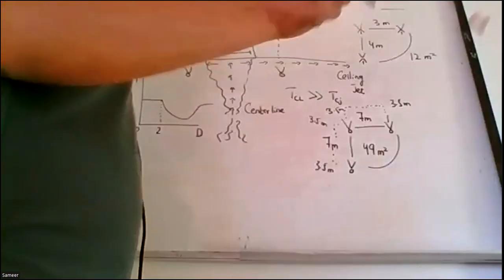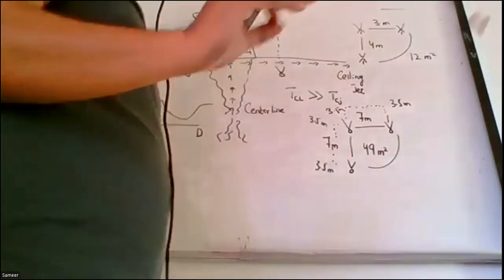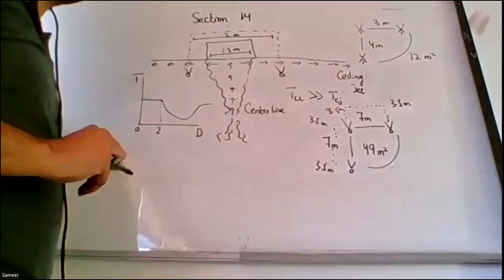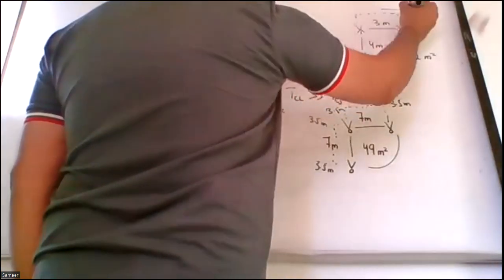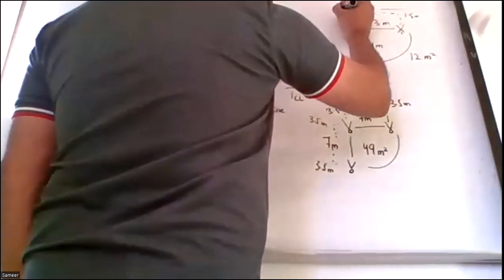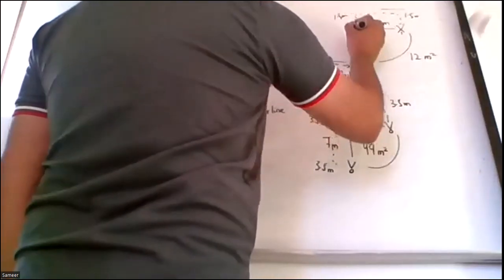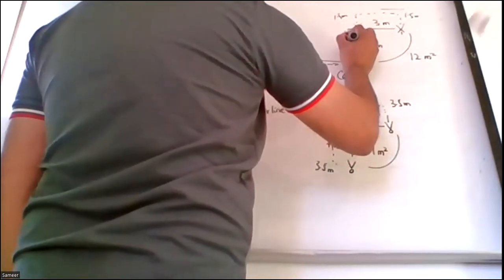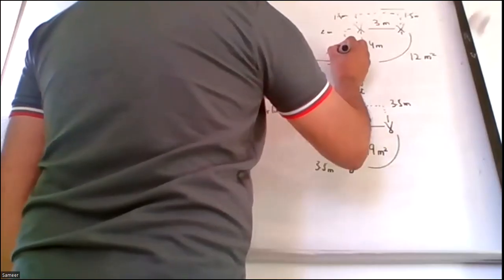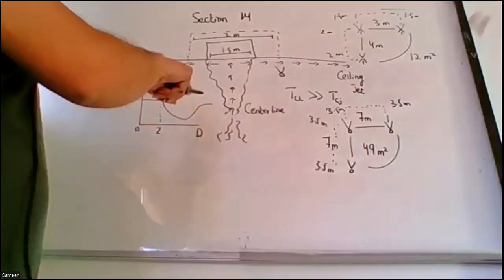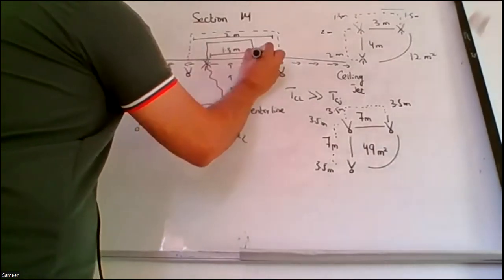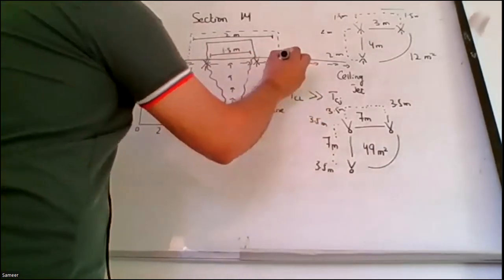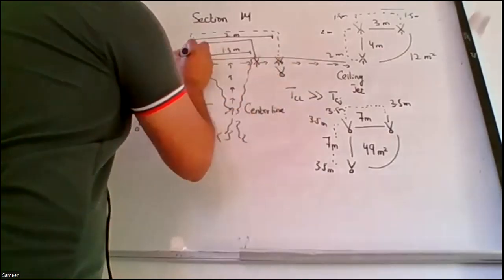It's 3.86 and 2.8 something, but let's say 3 and 4, just to make it easy. So for the sprinkler, 1.5 meters, 1.5 meters area of effectiveness, 2 meters, 2 meters. I cannot predict the center line, but I know at 1.5 meters my sprinkler should be there, and at 2 meters my sprinkler should be there.